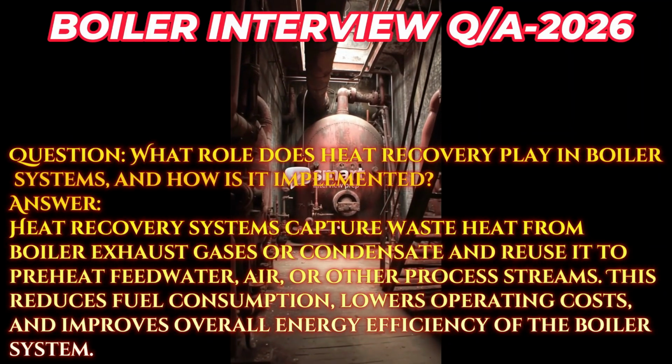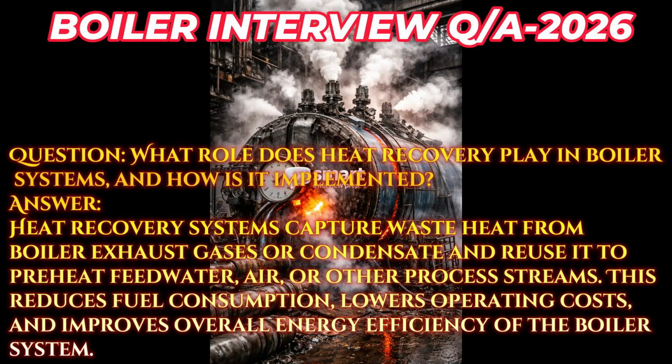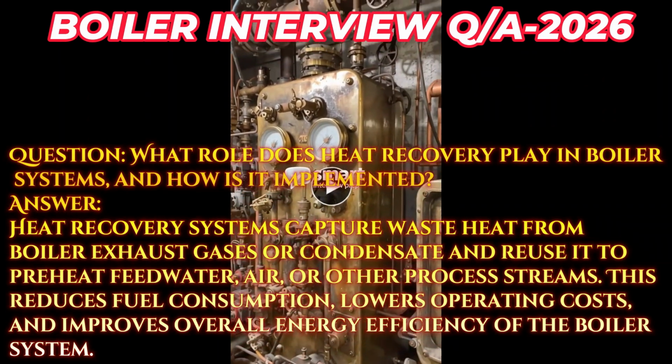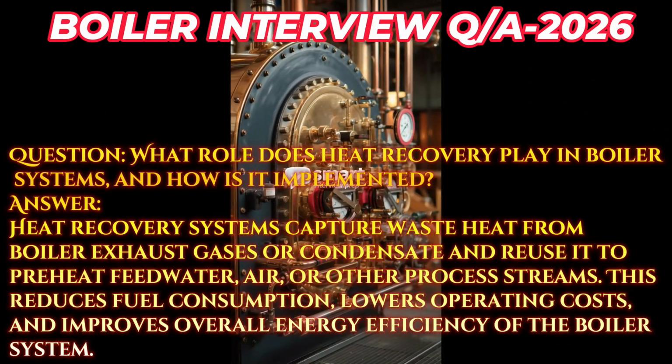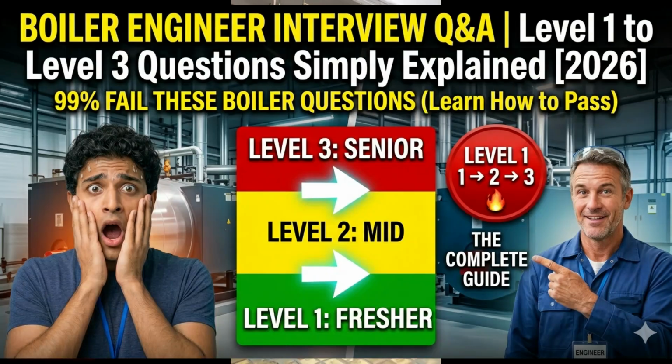Question. What role does heat recovery play in boiler systems, and how is it implemented? Answer. Heat recovery systems capture waste heat from boiler exhaust gases or condensate and reuse it to preheat feedwater, air, or other process streams. This reduces fuel consumption, lowers operating costs, and improves overall energy efficiency of the boiler system.